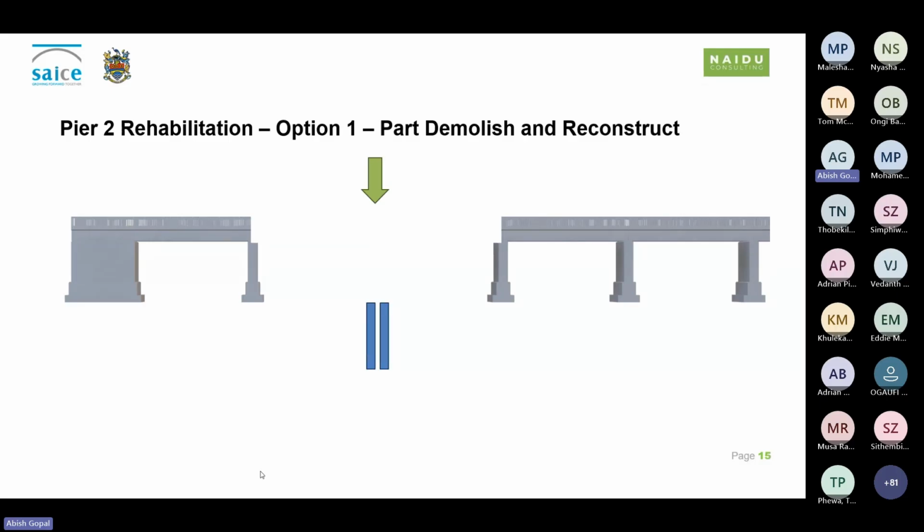Thereafter, construct piles and associated pile caps, along with reconstructing the pier and reconstructing the superstructure. Now, this in itself is a safe design, and it also mitigates the risks of further settlement and disastrous concerns during construction. However, there is an environmental impact and cost implication to this.